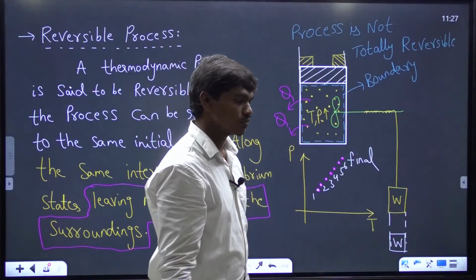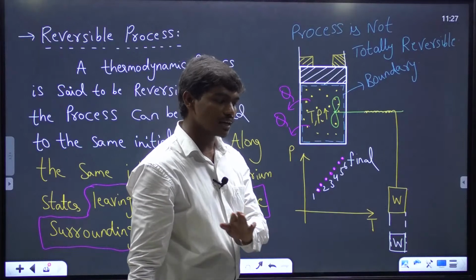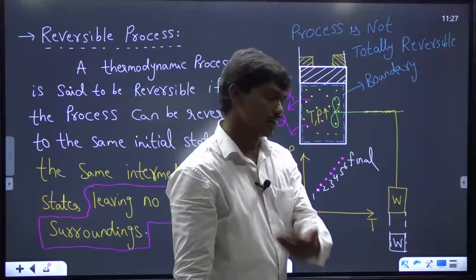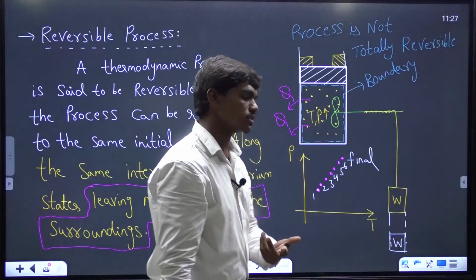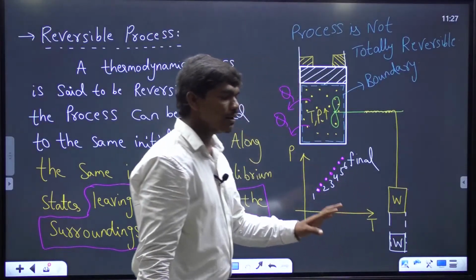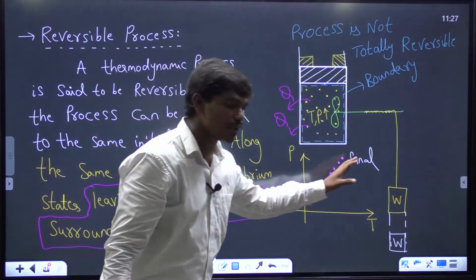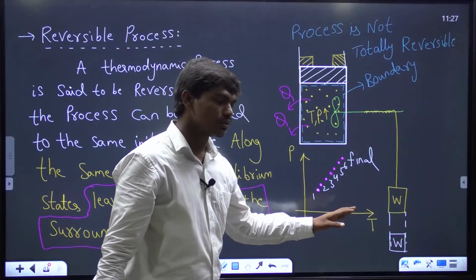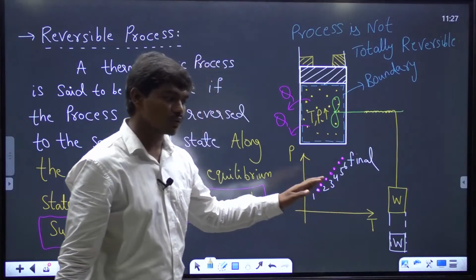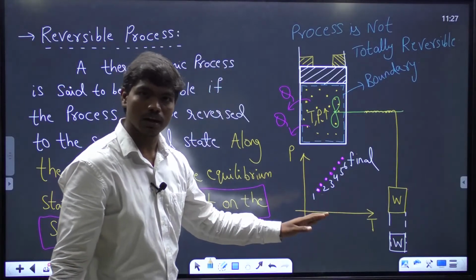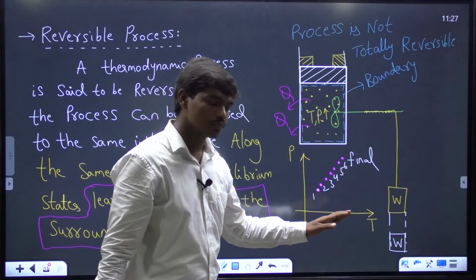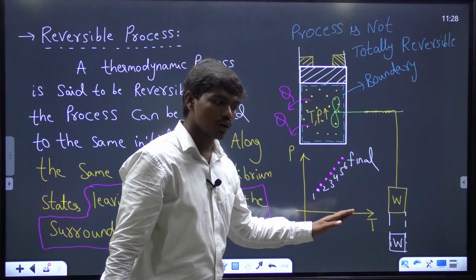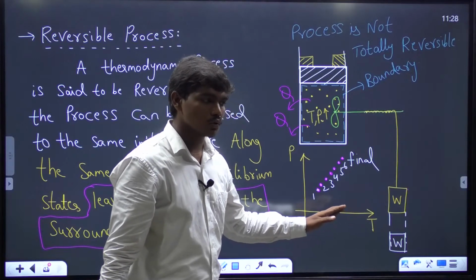Yes, a frictionless quasi-static process we consider as reversible, and we call that an isentropic process, whose name we'll introduce in later stages. So did you all understand why, even if a process is happening quasi-statically, it can't be reversible? Are you all okay till that point? So if a process is quasi-static, it need not be reversible. Okay, clear to all of you? Yes or no?